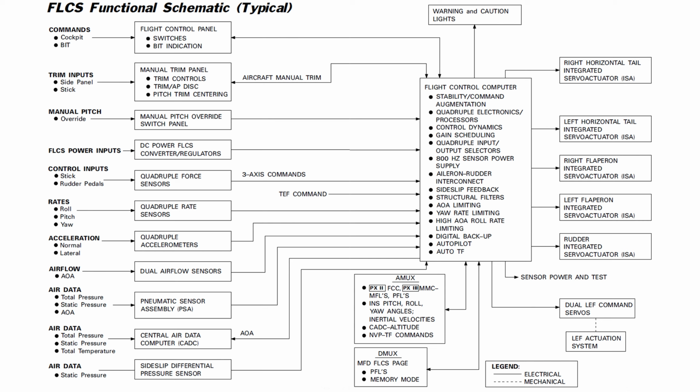Takeoff and landing gains is active when landing gear is down, alt flaps is set to extend, or air refuel is open below 400 knots. Below 10 degrees of pitch, FLCS operates as a pitch rate command system, switching to a blended pitch rate and AOA command system above 10 degrees. Roll rate is limited as a fixed value, independent of AOA, airspeed, or horizontal tail position.